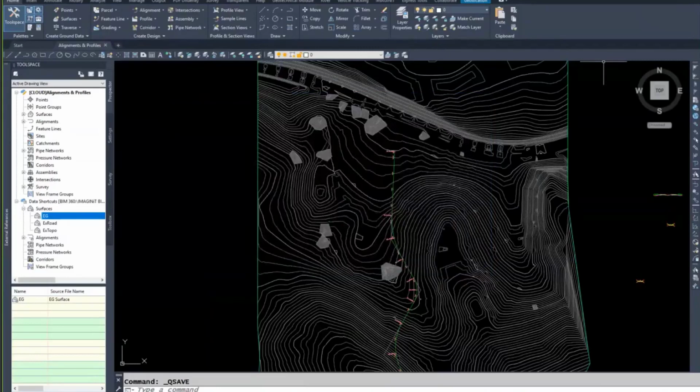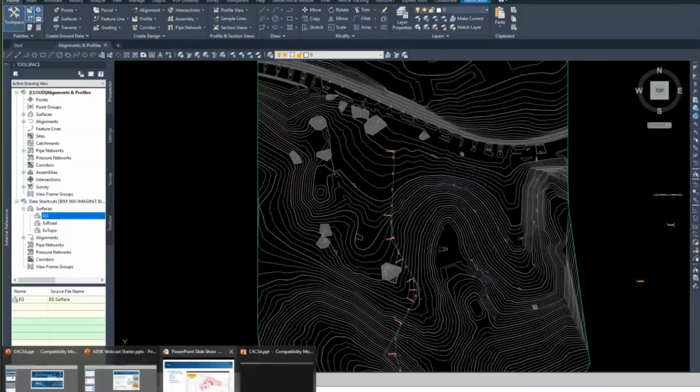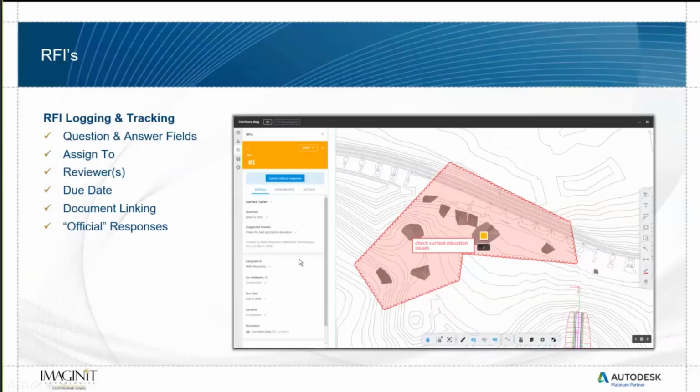And once that's done, back on the BIM 360 online portal, I would see a new version pop up with a new date and time indicating that that file has been changed and saved. And if I wanted to see what the differences were, I'd be able to click on that file within the viewer and launch that compare function. I'd be able to do either overlay compare, where I see red and blue, or the side-by-side slider bar compare, where I can see one version compared to the other as I slide that divider from left to right.